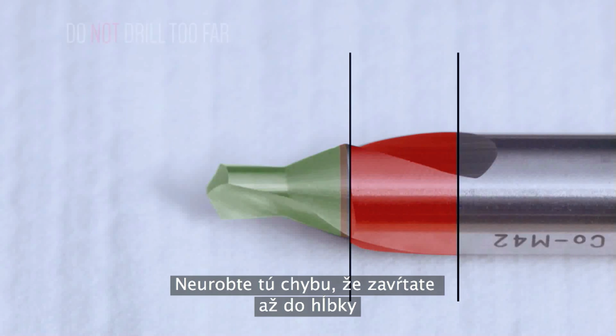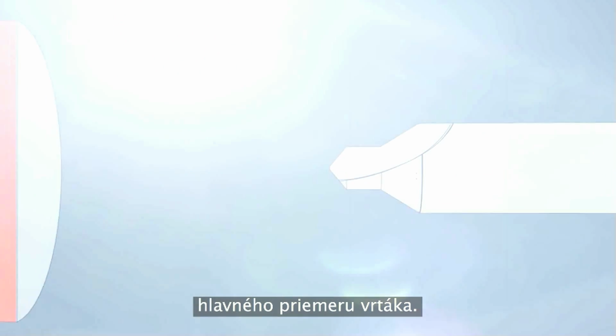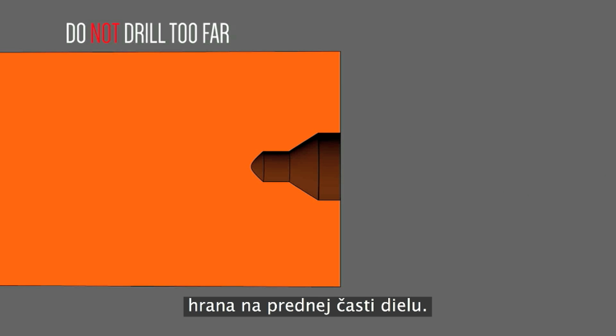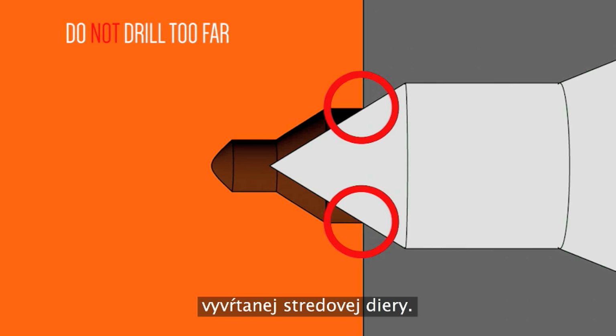Don't make the mistake of drilling so deep that you drill into the major drill diameter. Now, instead of a nice wide 60-degree flank, you'll be left with an edge at the face of the part, which will only offer a fraction of the engagement of a properly drilled center hole.